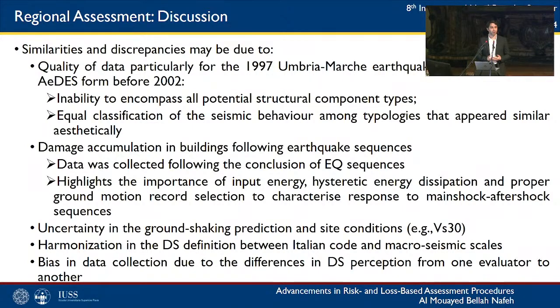And damage accumulation highlights the importance of considering other components in the analytical analysis, such as input energy, hysteretic energy dissipation, and proper ground motion record selection to characterize the response to mainshock-aftershock sequences. But perhaps more light will be shed on this matter during my colleague Nevena's presentation, so please hold on to your seats for that one.